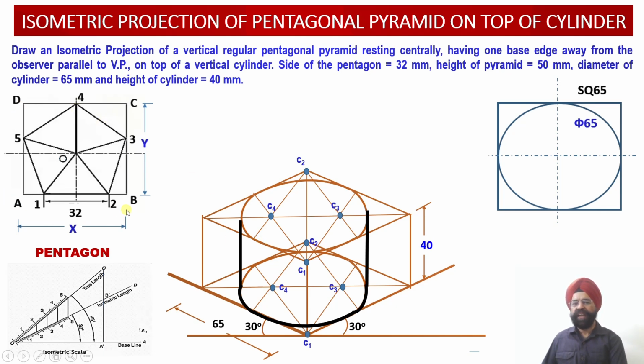But before we start working upon this construction, first of all I have to locate this rectangle on the top face of this particular construction, and the center of this pyramid should be matching with the center of this cylindrical portion. So for that purpose I need to work out the axis over here. Please see, the center points have to be located. This is my top face side. So I am going to obtain the midpoint of this edge.